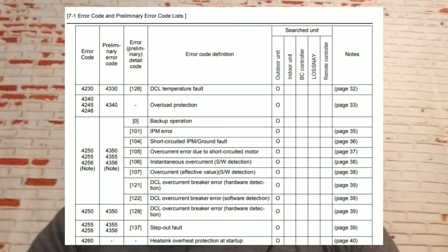If you're pulling these through the maintenance tool, get the detail code. You might not know what that is, but when you scan the system, look at the addresses and pull up the error log, it'll tell you a detail code. Write that down when you note the error, because the same error code can mean different things for different detail codes.